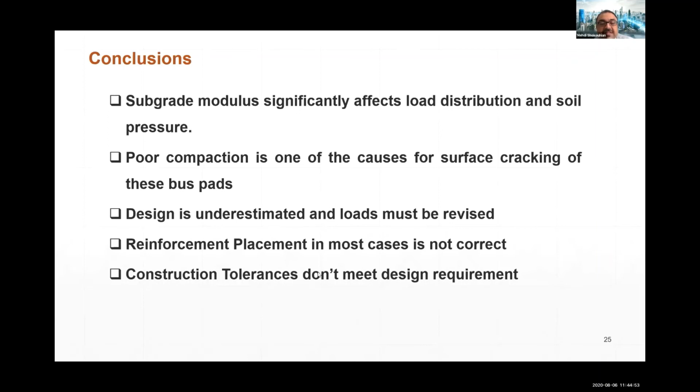Placement of the longitudinal wire mesh was considered to be close to the top face of the concrete slab, but based on the numerical results, the maximum longitudinal moment is positive, which requires reinforcement to be close to the slab's bottom. As per the site observation, the concrete clear cover was not the same at different places of the slab, which was caused by the concrete crews walking on the wire mesh during the pouring. This results in varying flexural capacity of the slab in different locations, which can cause concrete surface cracks at the top and bottom face of the boss pad.